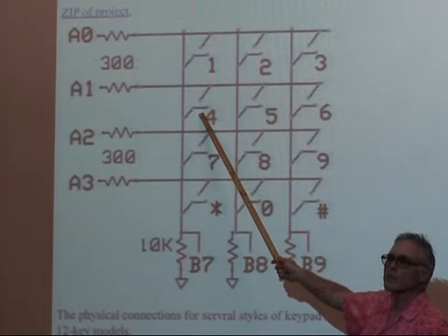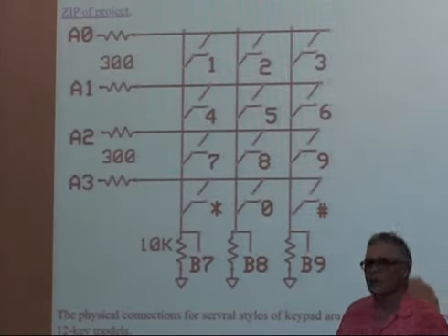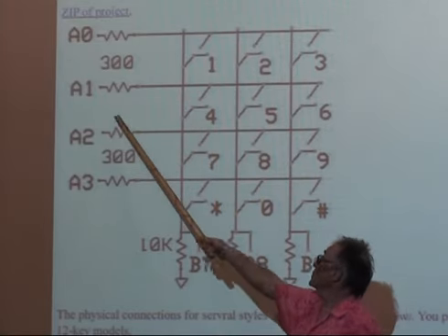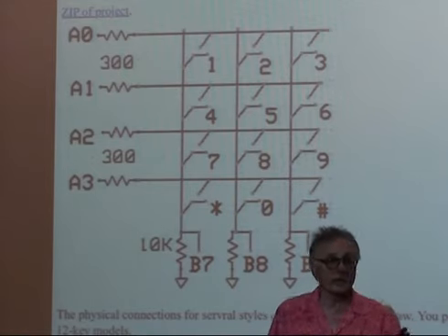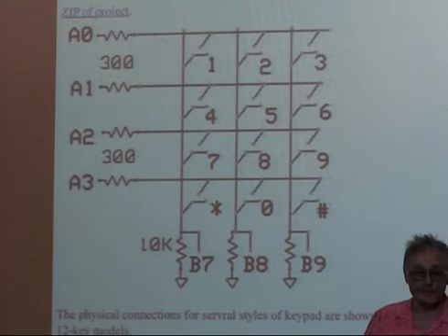But it returned -1. And so I had to think a little bit. Realized, oh, pin 4 is shorted to pin 7, A2 is shorted to A1. Both of those inputs are now right at the CMOS threshold. It probably doesn't work. And that's not a bug, it's a feature.